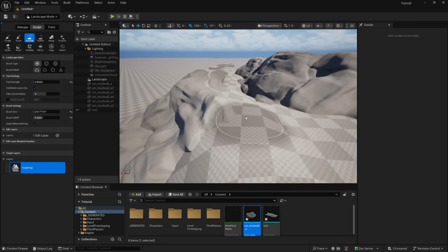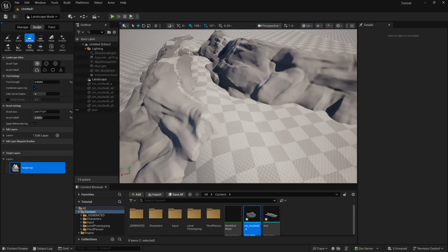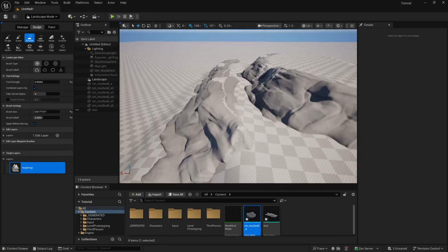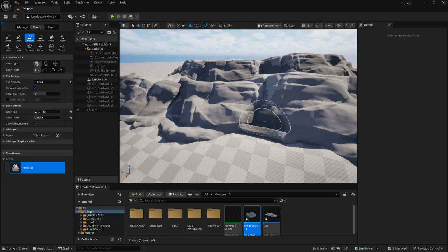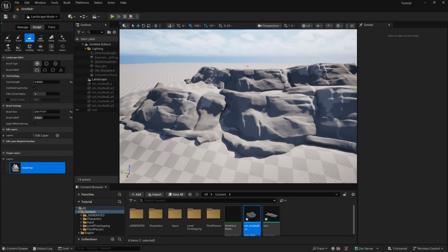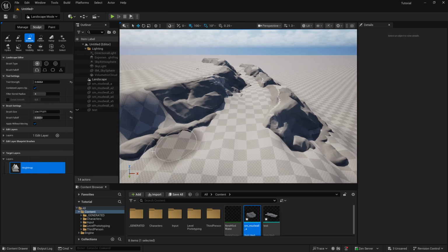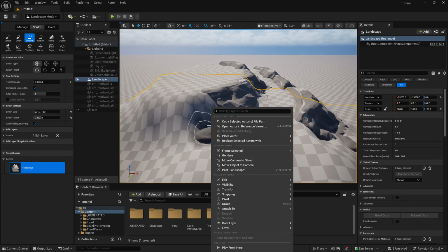And so all that sculpting terrain stuff I did in Blender, some guys were like, when are you ever going to sculpt terrain again and use it? Well, you can. You can sculpt in Blender, turn it into a height map, and bring it right into Unreal Engine. Not even a big deal. The terrain generators, of course, will generate textures or splat maps and things like that. Now, I'm not saying don't use a terrain generator, but do manually author it after to some degree if you can. You don't want to have it just spit out, you know? That doesn't make any sense.